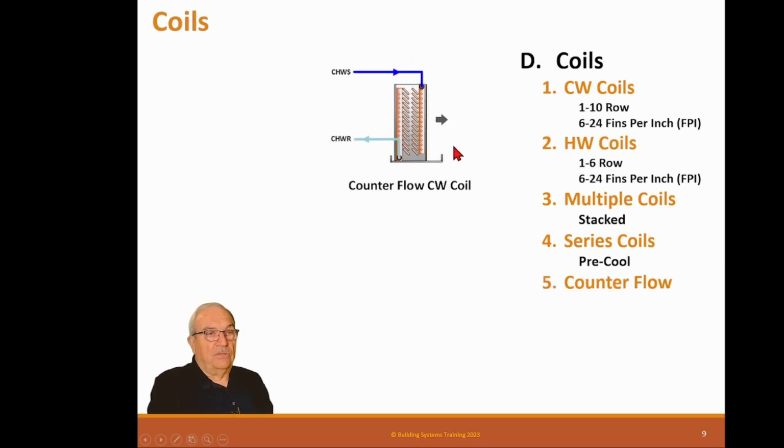And counterflow is important. This is the most important thing for chill water coils. You must, absolutely must, enter the coldest water on the leaving air side of the coil. So as the air comes through this coil and hot air enters and starts interacting with the cold water, it will start lowering the temperature in the coil till it gets to here. At this point, it will see the coldest entering water, and so it'll make the coil at this point the coldest it's going to be in this entire coil, and will dehumidify the air and it'll start bringing out the moisture in the coil.